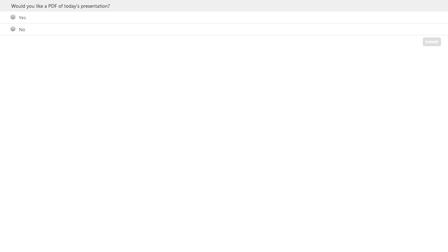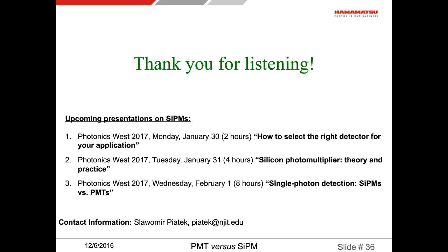In the case of PMTs, the range is much larger on the red side, extending all the way to about 1,700 nanometers. Those PMTs, however, need cooling since dark count rates there would be much higher because the energy barrier for the photocathode is much, much lower. Therefore, dark electrons can easily escape from the photocathode.